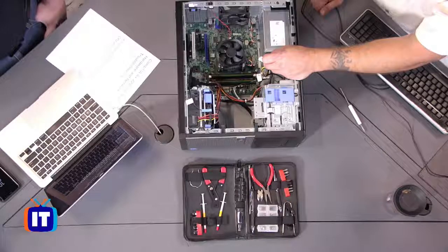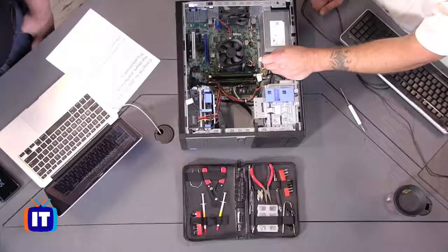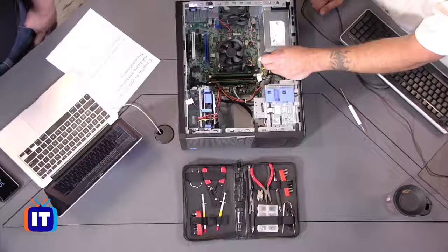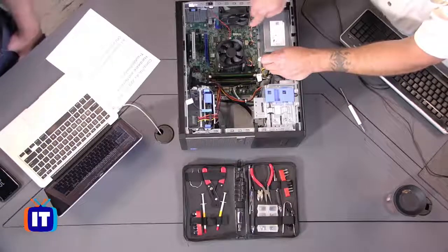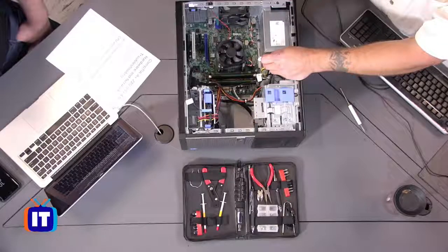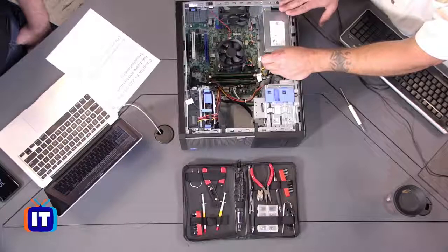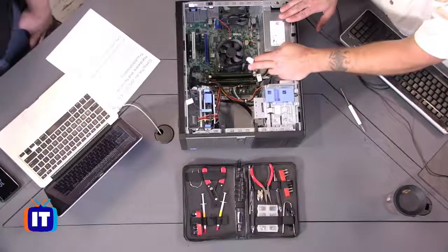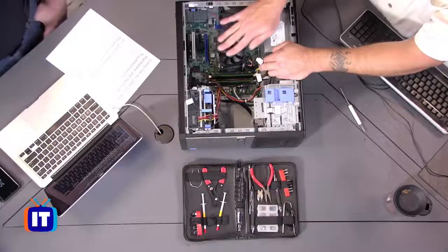So what it did is it noticed that I have power to the 3-pin and 4-pin Molex KK connectors on the motherboard that control the power to the fans, but I've got nothing on the CPU. So to protect itself, the motherboard said, no food for you, and it shut itself down right away. That's actually a good protection mechanism, letting you know that if the power supply goes like this and isn't giving you any power at all, you don't have to worry about damage to the CPU.